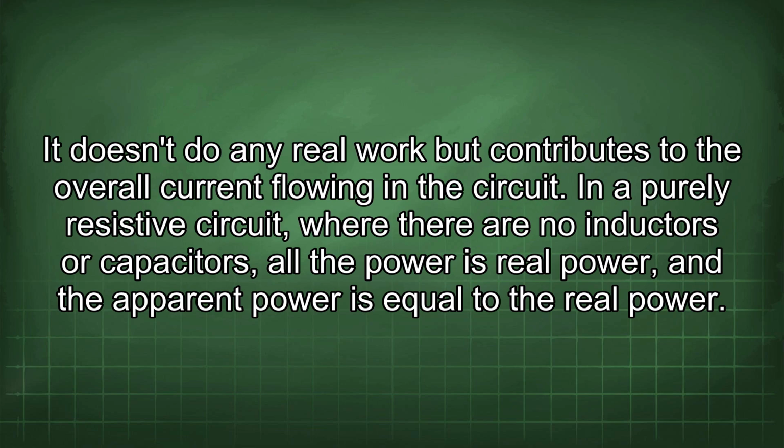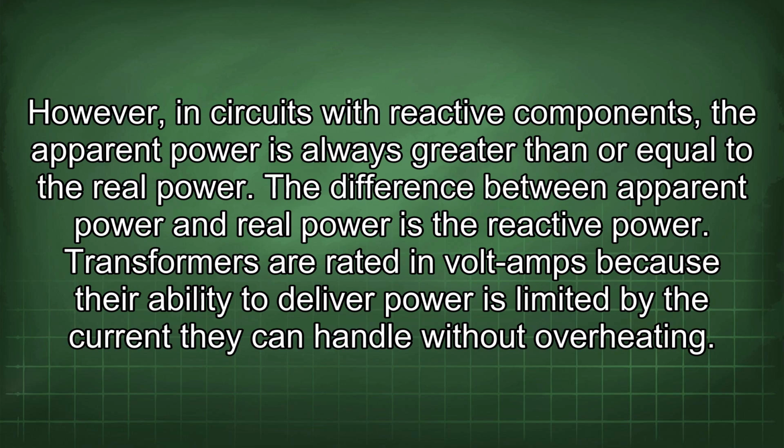In a purely resistive circuit, where there are no inductors or capacitors, all the power is real power, and the apparent power is equal to the real power. However, in circuits with reactive components, the apparent power is always greater than or equal to the real power. The difference between apparent power and real power is the reactive power.